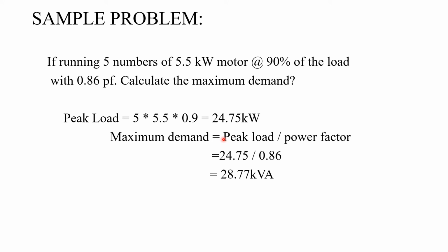So maximum demand is equal to peak load divided by power factor. Power factor is given as 0.86. So after calculation we will get maximum demand is equal to 28.77 kVA. That is the maximum demand of this problem.